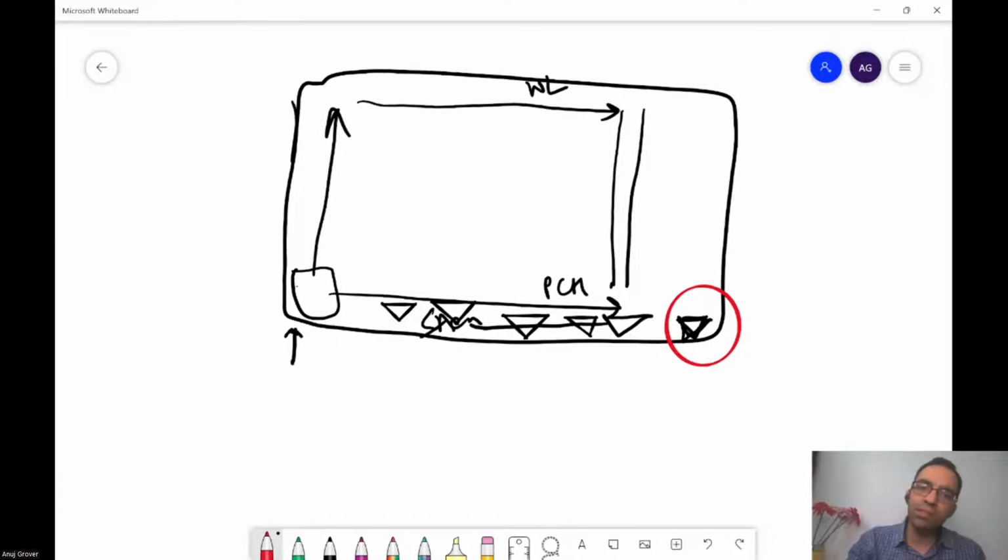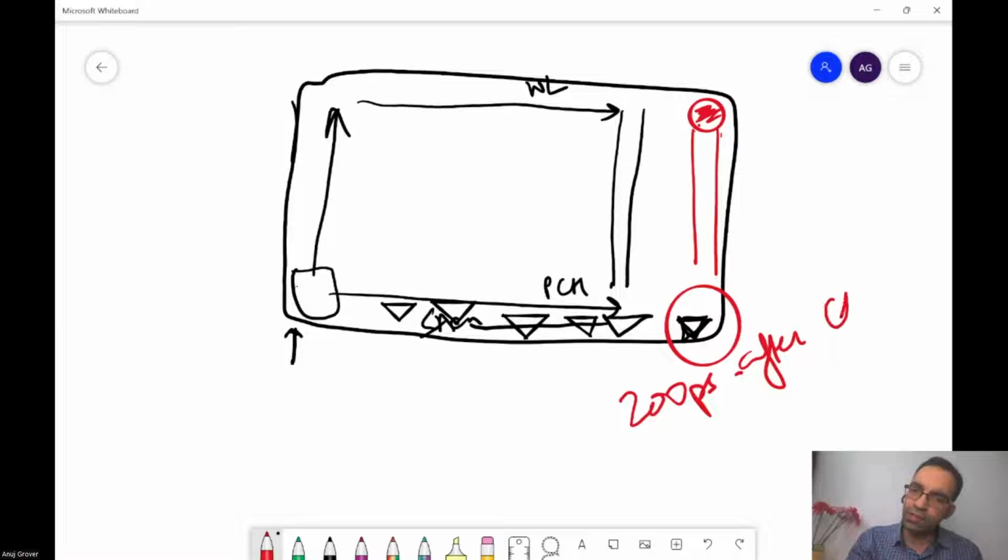Okay, let us assume that this has the worst case, and the logic that we use is that word line selection will be last for the memory cell placed here. Since word line selection happens in the end, the differential creation starts in the end. So this sense amplifier has the worst case offset. At any given time instant, say 200 picoseconds after CK, this sense amplifier will have the minimum offset.